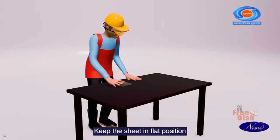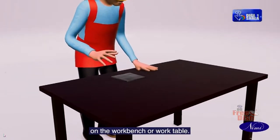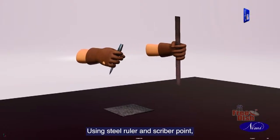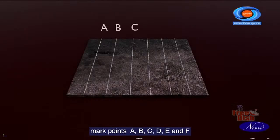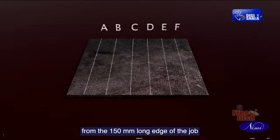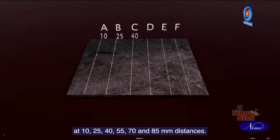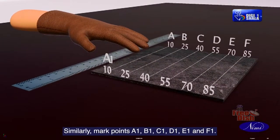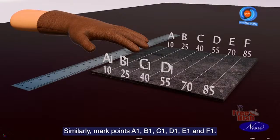Keep the sheet in flat position on the workbench or work table. Using steel ruler and scriber point, mark points A, B, C, D, E and F from the 150 mm long edge of the job at 10, 25, 40, 55, 70 and 85 mm distances. Similarly, mark points A1, B1, C1, D1, E1 and F1.